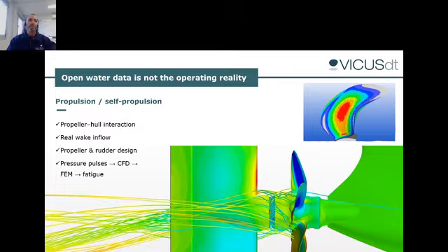And another topic that is very interesting has to do with how you can transfer those hydrodynamic pressures over the propeller, so you can analyze the structure with the real pressure fields. So this is the next step, the next level, when you couple the CFD with the structural analysis. This can be done for fatigue or for static analysis of your blades or your structural elements for a further optimization process.